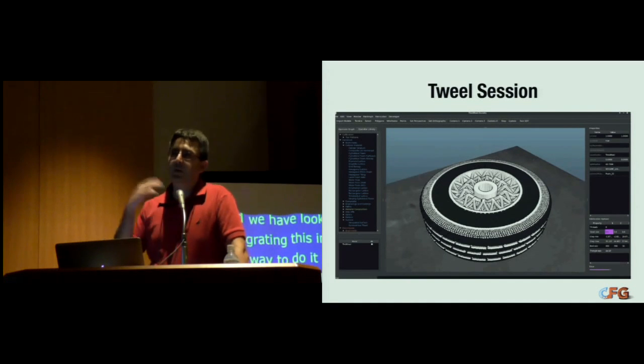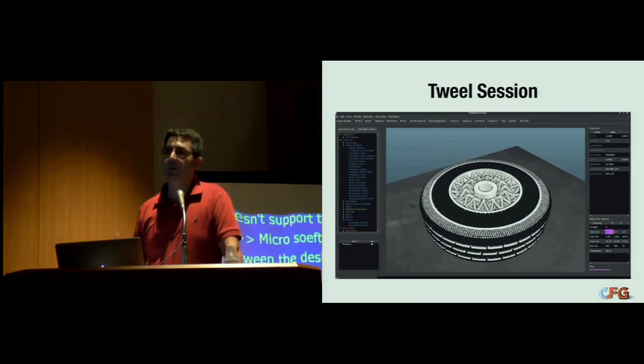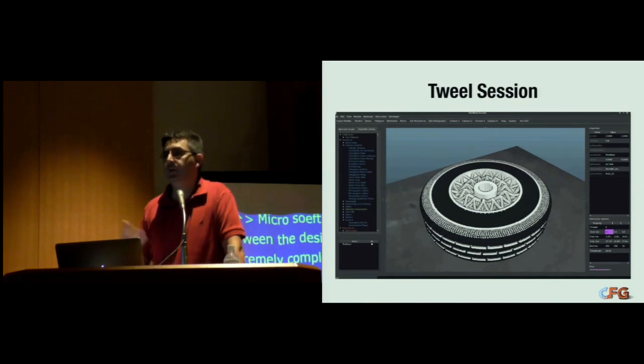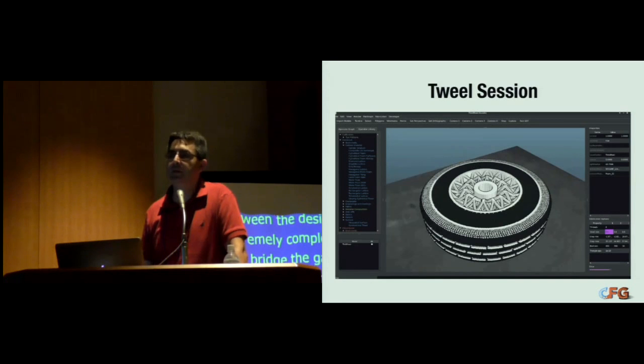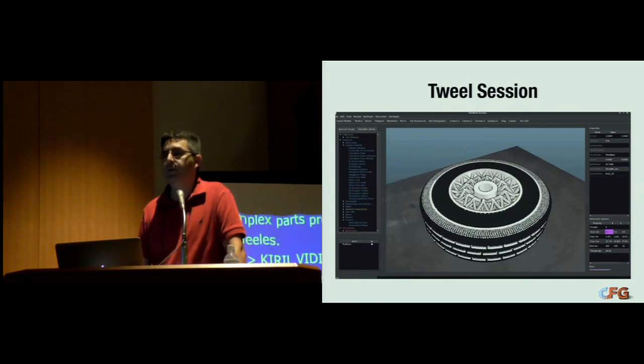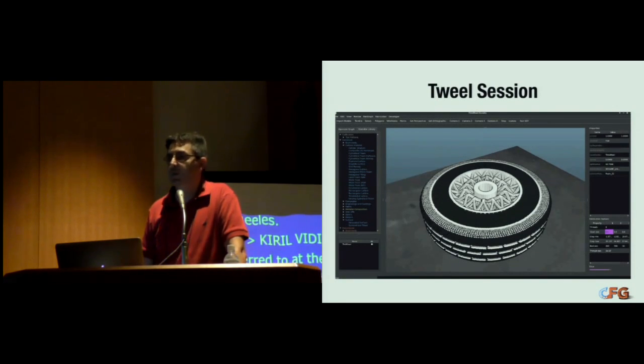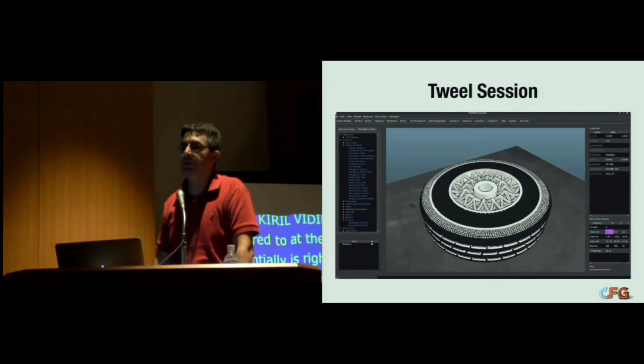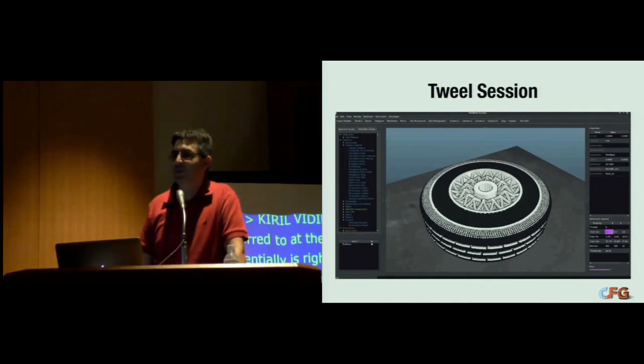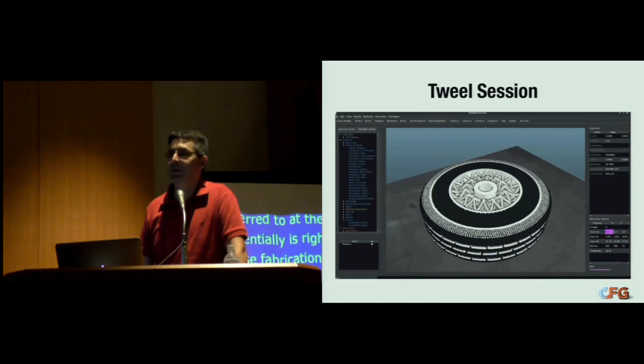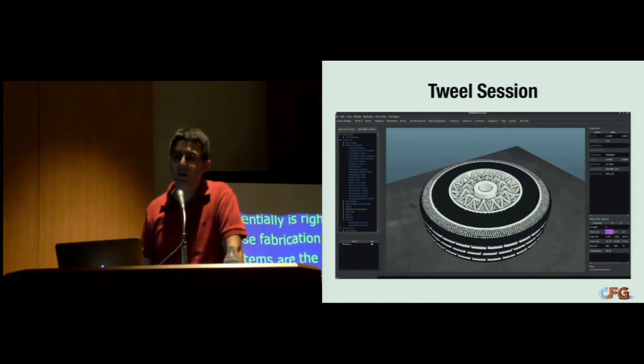Right. So that's basically what I referred to at the beginning, that right now we don't have these fabrication platforms, because 3D Systems and Stratasys are the only companies that currently sell commercial multi-material printers, and the materials that they use are not really durable enough to be used for functional parts. And of course the materials are extremely expensive, so they can't be really competitive with traditional manufacturing methods.